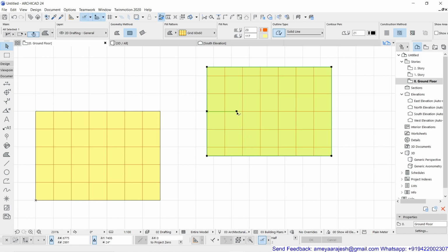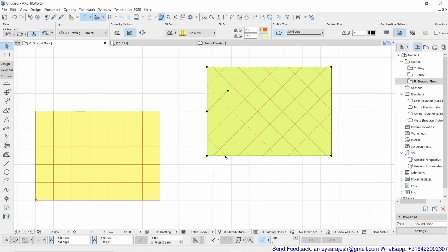For example, if I click on the other end of the vector, the right end of this vector, that is the field handle, and this time if I check, the same option is activated, Move Field Handle. You will be surprised that if I give some angle, say 45 degrees, my entire pattern will be rotated by 45 degrees. So now I am expecting that you will practice all these options. Try with some other hatch pattern if you want, but at least get basic knowledge of this, and then follow the next clip.